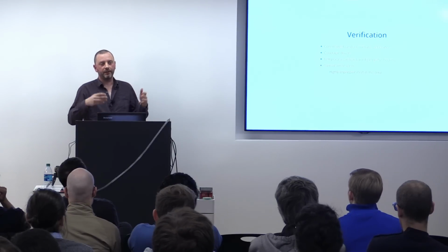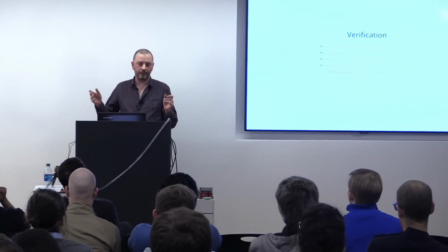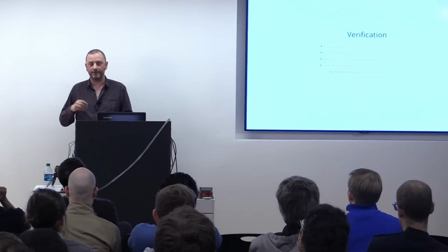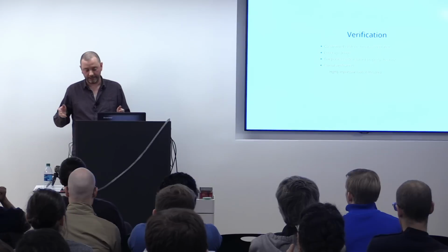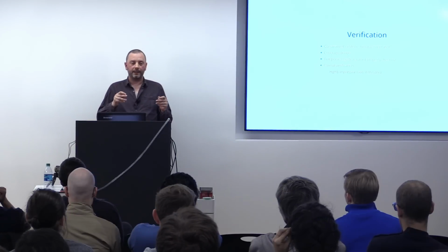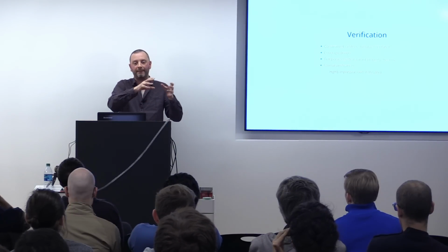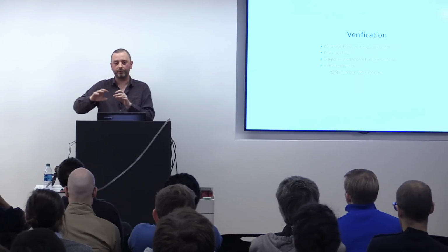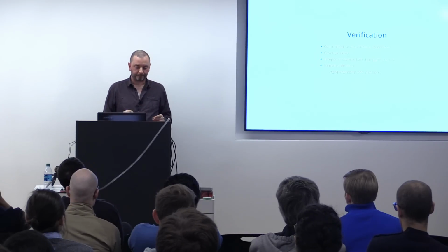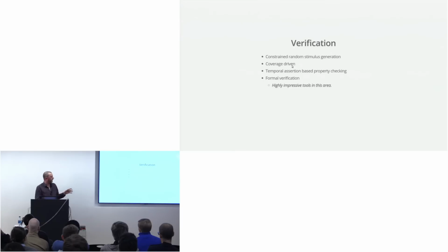For example, say you've got a network packet processing core, and it only works with some specific protocol. You can tell the tool that the packet should look a bit like this, and it will generate a bunch of random stuff. Alongside this, the coverage-driven frameworks that the tools provide allow you to dig into interesting parts of the design automatically.